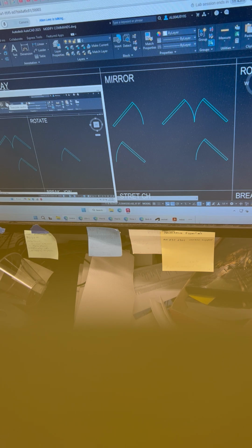All right, point your cursor straight up and go ahead and click to pick the end point of the mirror line. All right, now it says, do you want us to erase the source object? In this case, I simply want the object to be reoriented. I don't need the second object there. So I'm going to say yes, erase the source object.